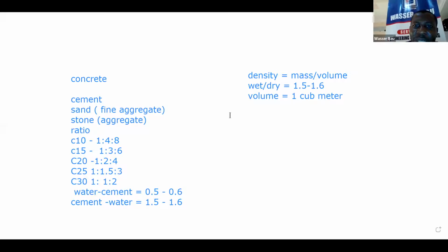Good. Just Sanusi said gravel 1,700. He now says cement 3,100. Just Sanusi, it's not the cost, it's the density. Cement is even lighter, it's less dense than sand. So there's no way cement can be 3,100. Cement is like dust, like silt, it's very light. So the density is close to 1.